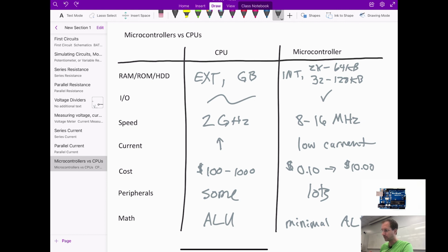And so if it sees a division or a multiplication, it generates the code in assembly to do that for you. If you're talking about floating point, so numbers with decimals in them, or real valued numbers, doing floating point arithmetic is extremely expensive on microcontrollers because it's all simulated in software. And so adding and multiplying and dividing real valued numbers is very, very slow. So this is largely the difference. And you can see here that they occupy very different